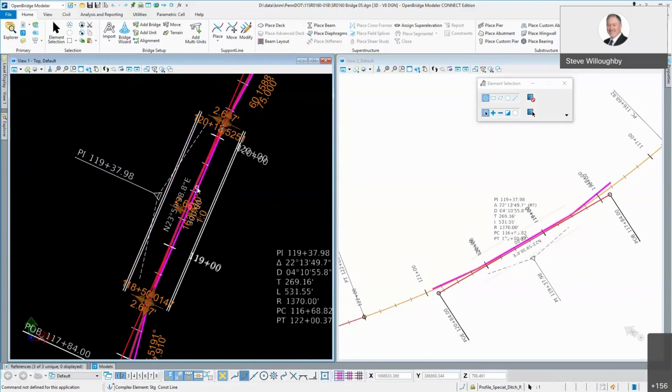When I went to model the bridge, and I initially only had this single line right here, it was unable to model the deck as a solid. And I kept getting an error about some crossing lines, or I don't know, it just couldn't create that solid. So I reached out to the developers and the product manager, and we had a quick little call, and they explained to me that basically this line right here, and the bridge itself is heavily skewed. We didn't really mention that earlier, but the bridge is very heavily skewed here.